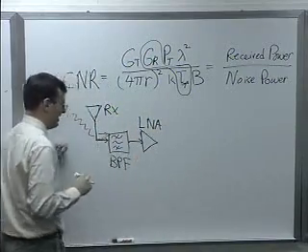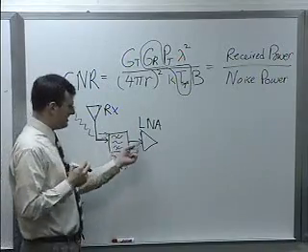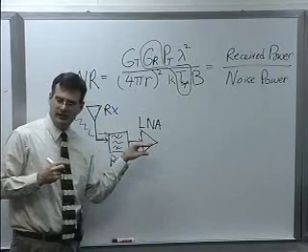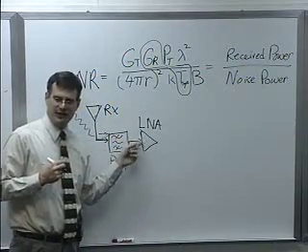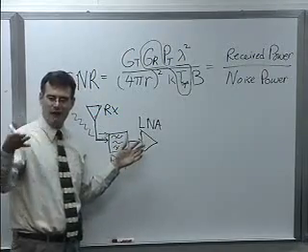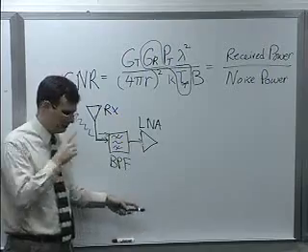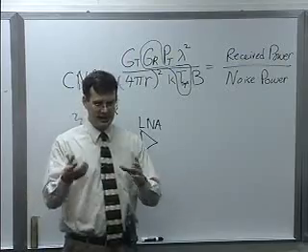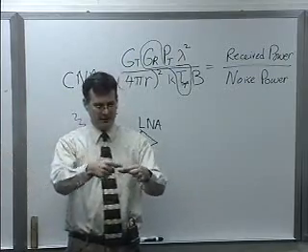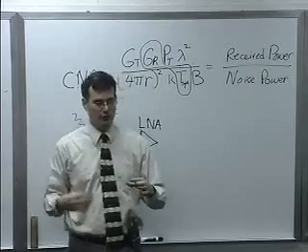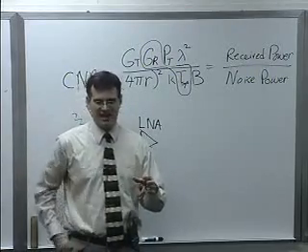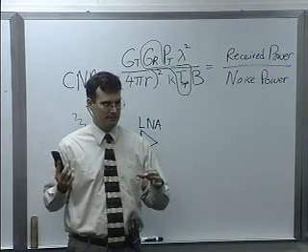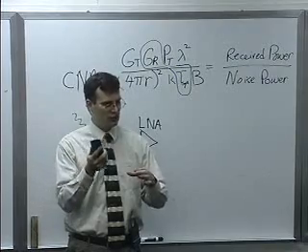LNA, low noise amplifier. Because it's an amplifier, if you've got a lot of signal energy coming in on the input, you could conceivably saturate it, even if you didn't intend it, even if there's some out-of-band energy. So for example, let's say I've got a 915 megahertz wireless LAN. I've got maybe my laptop, and it's got a little card connected to it. Normally we use 2.4, but there are some that work at 915. And I've got a cell phone that's still using one of the 860 megahertz channels that are transmitting voice and control channels. And I get those close to one another.